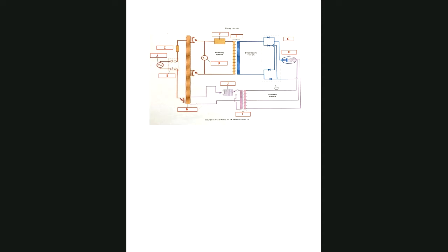Okay, so what happened to my incoming voltage with a step down transformer? What happened to that incoming 220 volts? It goes down. Okay, yes, it does. Do you remember the range that it goes down to? No. Okay, it goes down to 6 to 12. And so if the voltage went down, what went up? If the voltage goes down, the current goes up.